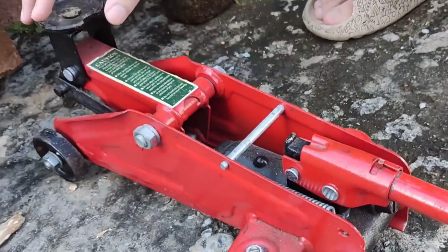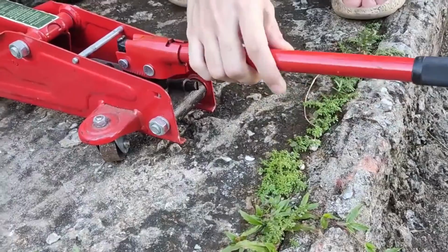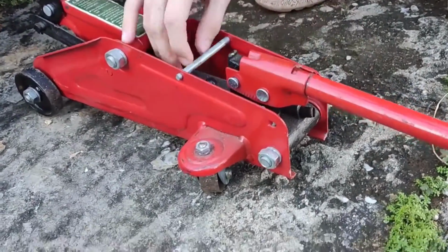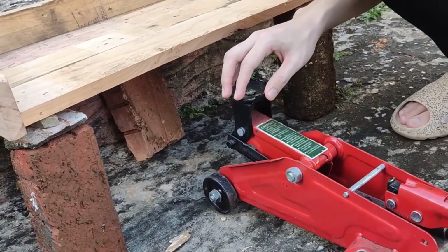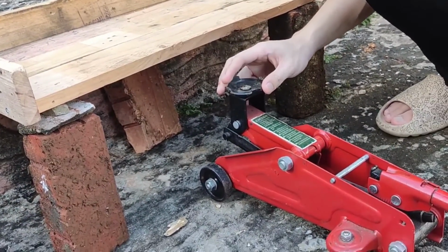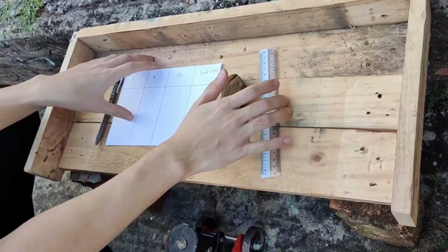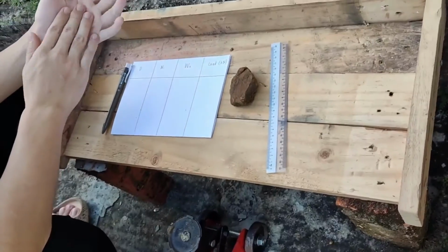We can increase the length by pumping the hand pump. As we do the action, the hydraulic fluid will flow from the hand pump to the hydraulic piston and the length will increase. This is how we increase the load in kilonewton onto the rock sample. This is where I would usually do the measurement before putting the rock sample to the PLT machine for testing.